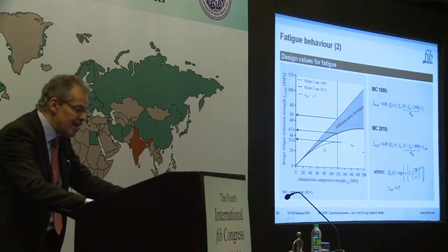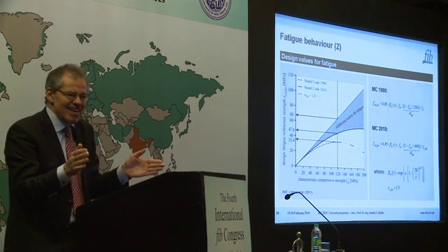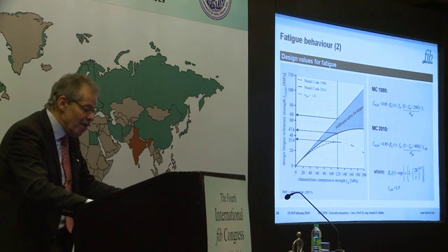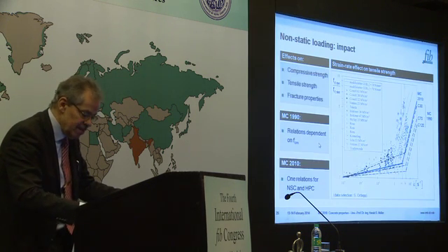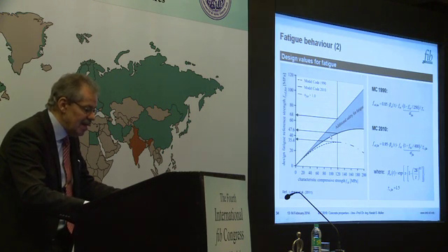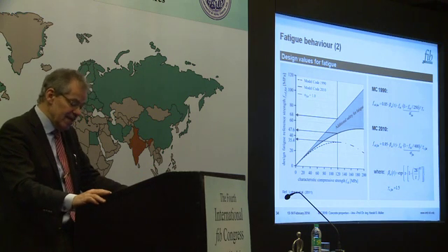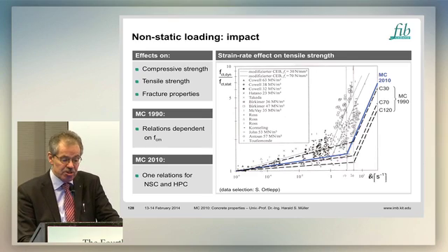This is a design value of the old Model Code. If we had kept the same, we would not take profit of the increasing strength. We had to modify it. And we now modified it. It is now this curve. Oh, sorry, go back. It was going too much. It is this curve, which is now valid, but there is some room for improvement, or, to say it otherwise, this is additional safety for fatigue, which is now included. These basic formulas, I think, still have to be improved in the future.